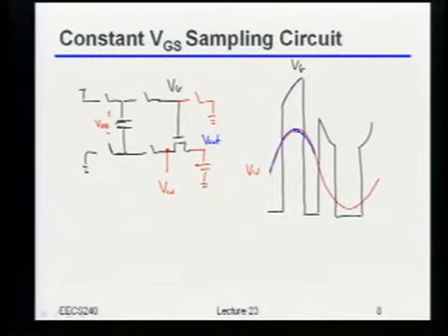Why do you usually say that you used a certain VDD in the process to begin with? We don't blow up your gates. So you don't blow anything up, right? Because let's say it was your 90 nanometer process and it was a 1.2 volt supply. If you put 2 volts onto those transistors, they pretty much literally pop.